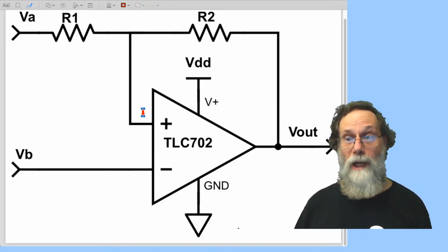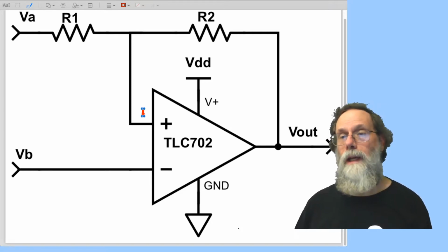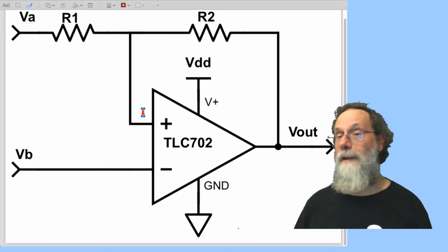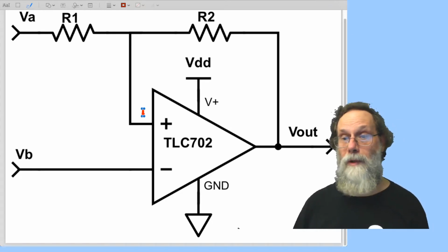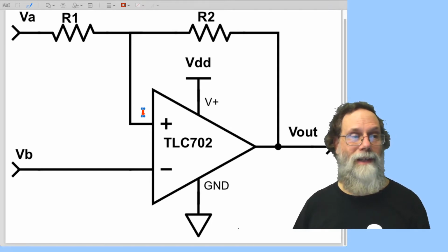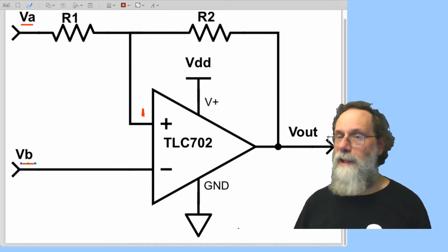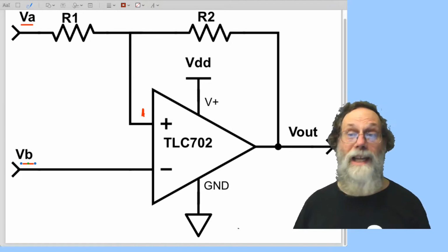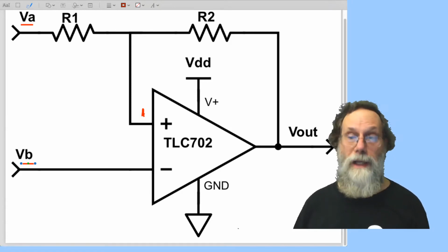And that's about the only time we do it, because the positive feedback, that loop, gives us memory rather than the sort of gain control that we're usually trying to get from an op-amp circuit. And the two inputs, VA and VB here, are just like the two inputs of the generic negative feedback op-amp circuit. Depending which way you hook them up, we get different results.